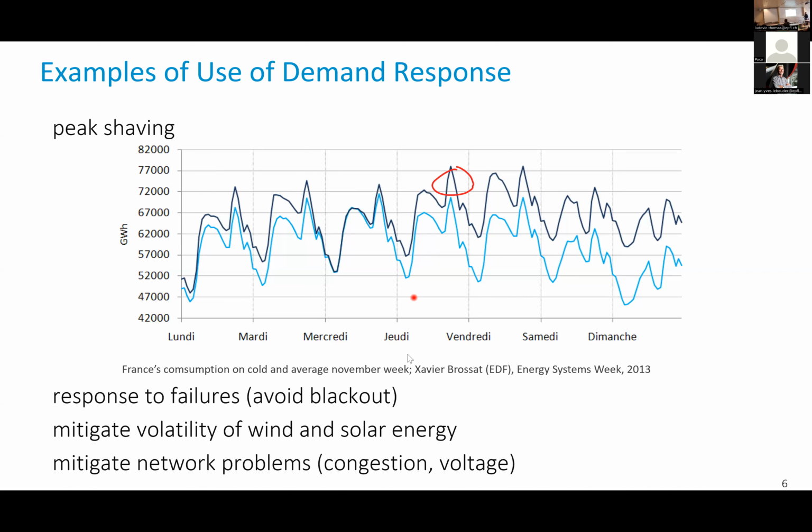There is worse than load shedding, which is called blackout. Blackout is when there is no power and it comes as an accident. It can come due to a failure in the control of the grid. As we have seen, the grid is controlling everything doing OPF. We've seen that OPF is a hard problem to solve. If you make a mistake in your OPF, or your software has a bug, or the nonlinear solver doesn't converge, there might be problems that cause something similar to a hardware failure.